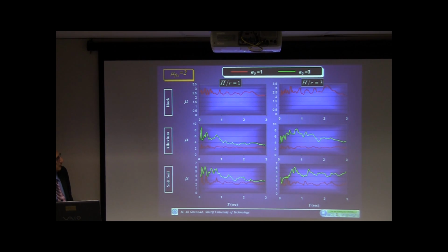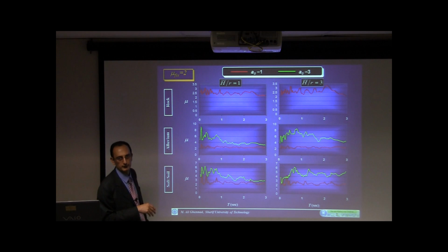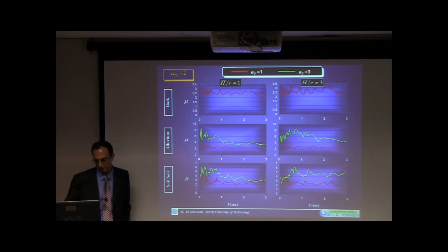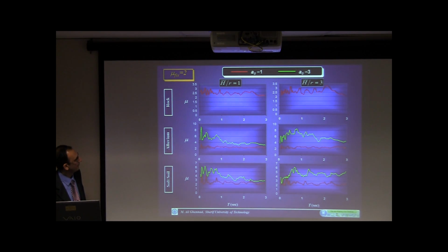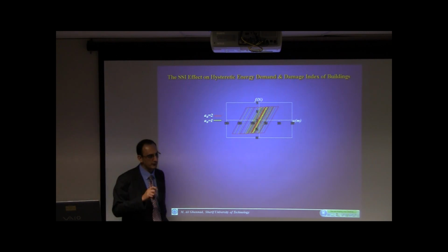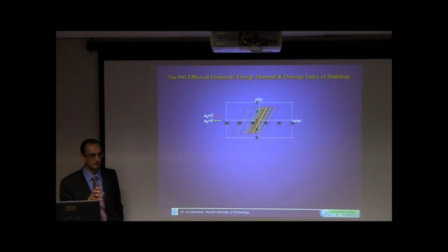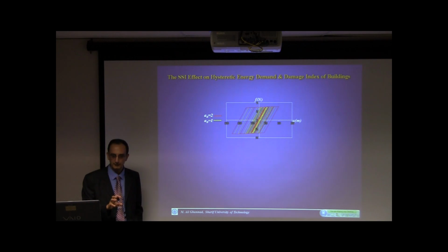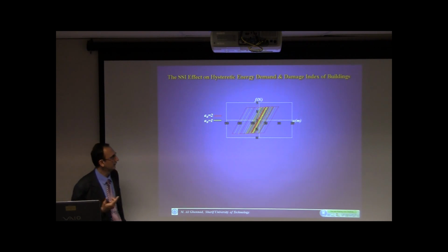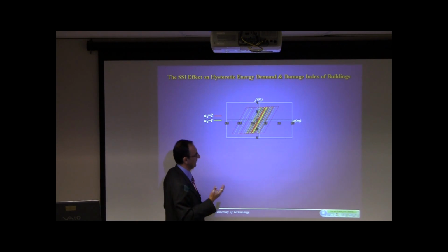And this is the average for 24 ground motions recorded on the alluvium site. And again, it can be seen that there's a large difference between the two results. Okay, I go to the hysteretic energy demand. Of course, when you change the system, it means you introduce the soil beneath the structure, the hysteretic behavior of the structure changes. And it can dissipate more energy or less.